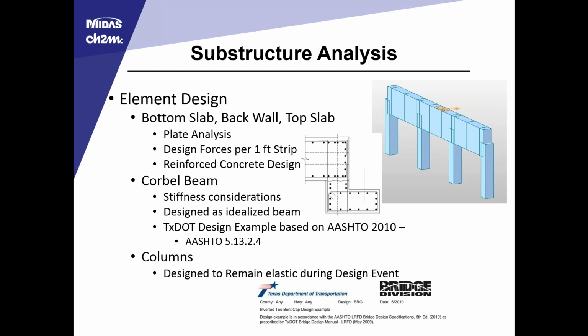For the element design, the slab elements were analyzed as plates and designed with a 1-foot strip width using reinforced concrete design. There were some stress concentrations around the columns that were taken into account, but for the most part, the reinforcement through the slab was consistent, and there wasn't significant variation in the spacing.